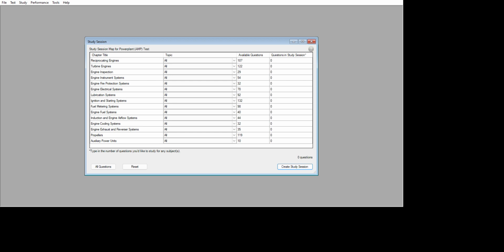If a new breaker point is installed in a magneto on an engine, it will be necessary to time the magneto internally and the magneto to the engine. As the aircraft engine's speed is increased, the voltage induced in the primary coil of the magneto increases.